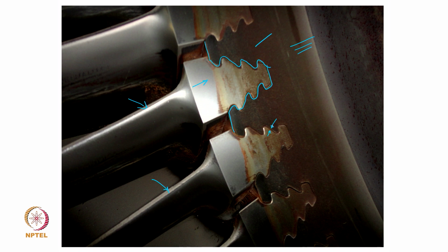So, these gaps are responsible for some friction damping at the root, and as the blades vibrate with large amplitudes, there will be small interface displacement and some slip motion between the stationary component and the vibratory blade component at the root, and that generates some amount of damping which can help dissipate the resonant vibratory displacement of the blades. So, this is one place where the Coulomb damping is actually designed in.